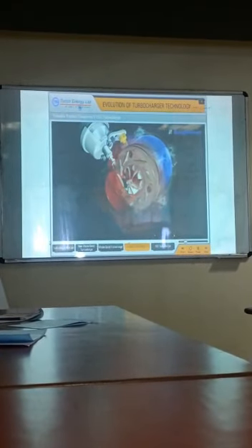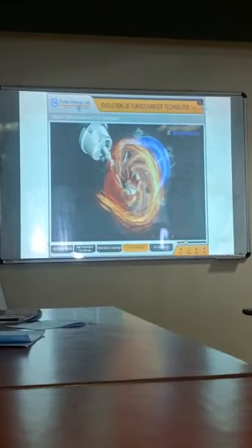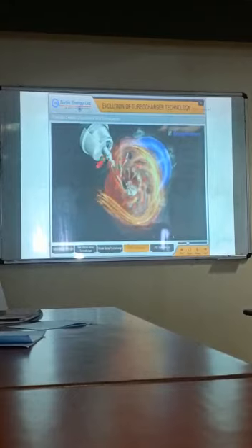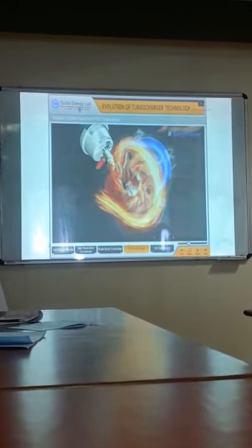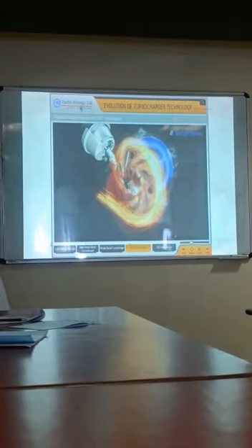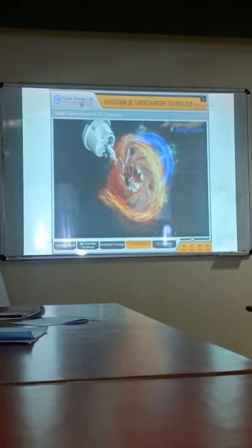The turbine housing has a set of vanes placed in the exhaust gas passage area above the turbine wheel. The exhaust gas entering the turbine housing has to pass through the vanes to reach the turbine wheel. Initially, the actuator and vanes are partially closed. The actuator rod moves down and opens the vanes. Though a higher amount of exhaust gas is entering the turbine housing, the turbine wheel speed is slow because of open vanes.